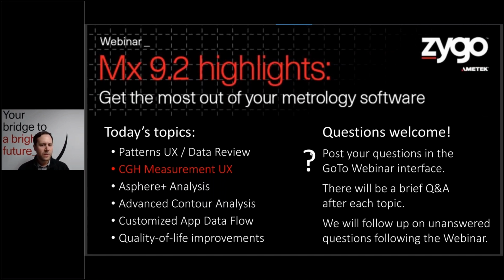Another issue that we will run into and need to address when using a computer-generated hologram are distortion effects when measuring through a CGH, especially if you're doing any sort of sub-aperture polishing techniques that are typically used with aspheres. It's really important to know that your surface error or your surface feature is laterally dimensioned at the right position if you're going to correct that in a post-polishing step. And we'll take a look at how we are doing that remapping in MX as well.